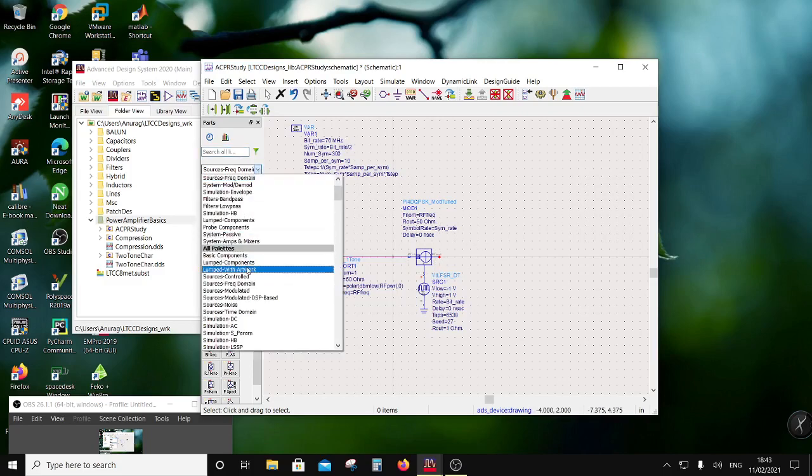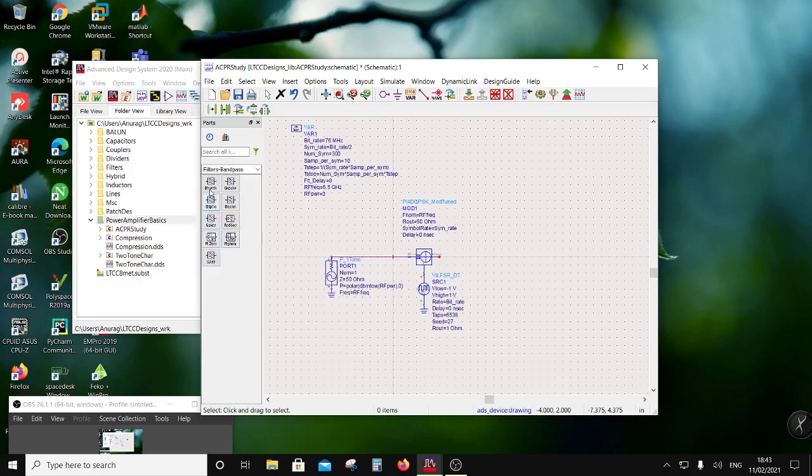So here I will put a DSP filter. So I will go to filter band pass. Okay, and I will look for a raised cosine filter. So that's a raised cosine filter, correct? And here I am going to have alpha. Alpha is basically excess bandwidth. So if there is a cutoff window, as we have seen in the filter, we have certain excess bandwidth. So that is 35% here, 0.35.